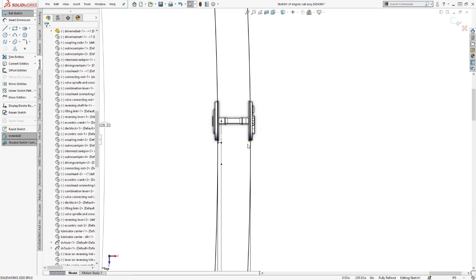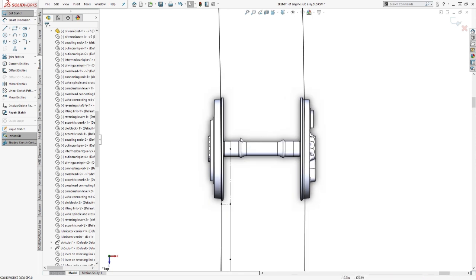Well, in a car, they put in a differential. You've got the motor input, and it basically will divide between the two tires based on force, and if they're in good contact with the road, then it's basically going to find its own ratio as you go around a curve. Going straight, it would have a 1-to-1 ratio. Well, we can't use a differential on a train.